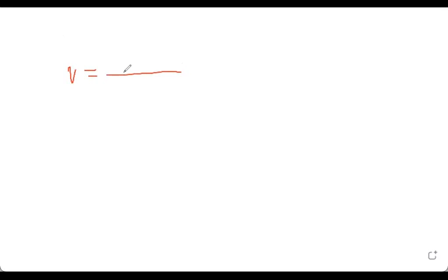simply multiply the one sun, which is 1,000 watts per meter square, by the area, which is very normal, because as you know, this is a power density. This one sun condition, this 1,000 watts per meter square, is a density of power. So you have to convert it into power, so you can divide power over power, because in the output you have the power, which is simply V open circuit times I short circuit times the fill factor, if you remember. So in this case, you multiply times the area.